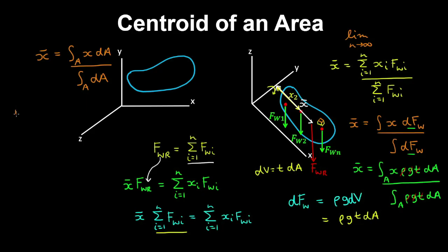And to obtain an expression for the centroid in the y direction, well, you take moments about the x-axis, and you'll obtain an integral of y over the area, over the integral over the area of the body.